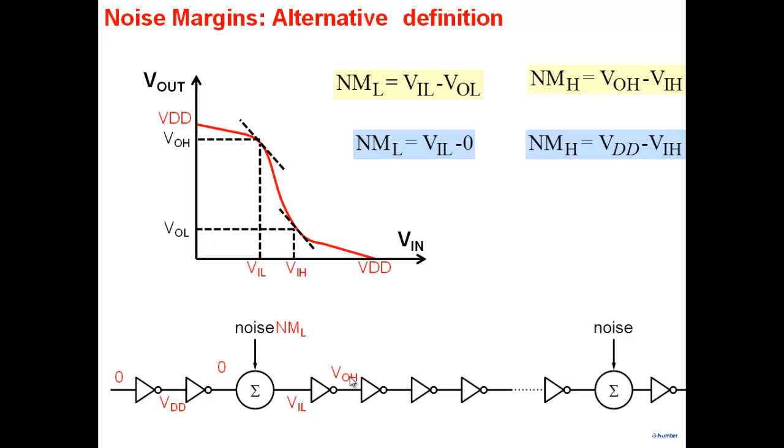Does it make sense what they're saying? But note that they're assuming it's 0, VDD. They're not assuming there's noise here, or here. If they assume noise at every place, this definition goes wrong. It will not work. But if you assume that most of the time it is noise free, and noise gets injected at one of the places, then this definition is fine. So you get VOH here, and eventually the system will recover and you will get VDD here. They say, well, the system recovers, so noise is a rare event. Again, how much noise can I add and still have things work fine? So they will use this definition, because then you'll get VIH and you'll get proper values.